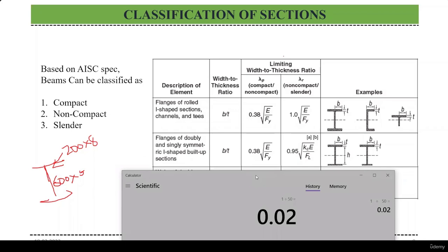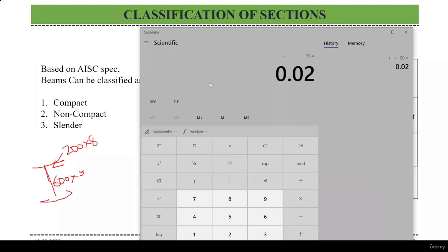Whereas Fy is the yield stress of the material which we are going to use in a PEB industry. Generally, high yield steels are used in PEB industries. For example, in our discussion, let us take grade 50 steel, ASTM A572 specification, which has a yield stress of 345 Newton per mm square.